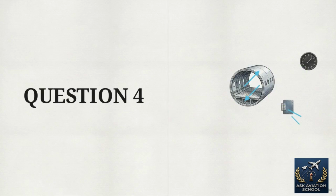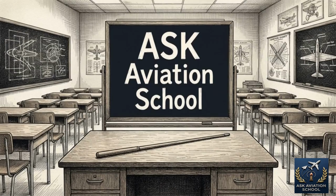Question 4. What is the primary function of the outflow valve? It regulates the exit of conditioned air to maintain the target cabin altitude and safe differential pressure. That covers the A320 pressurization logic.